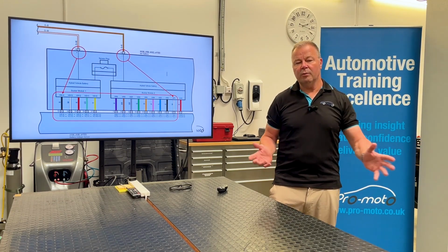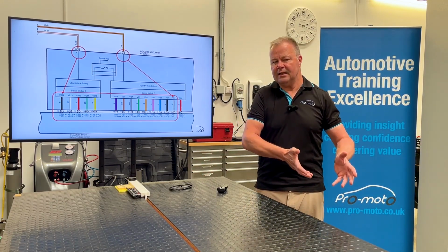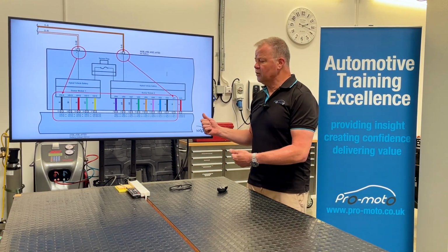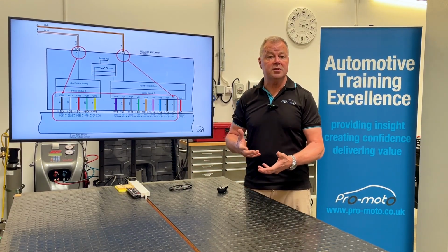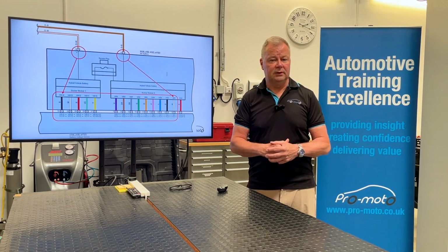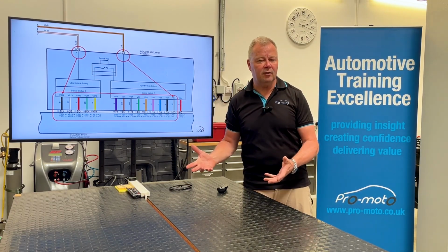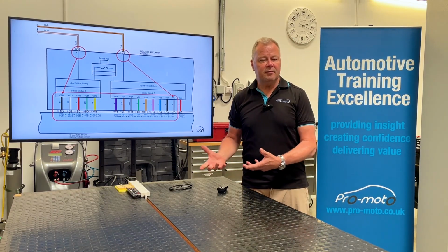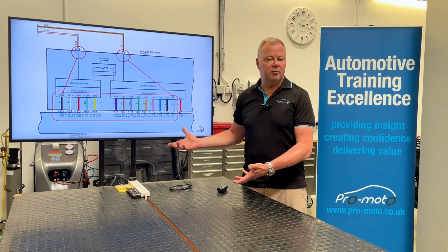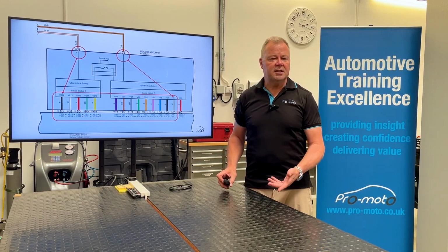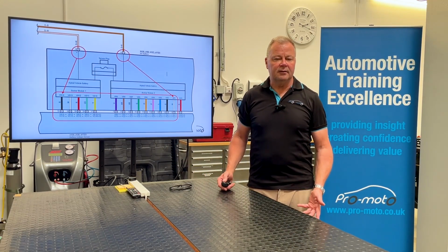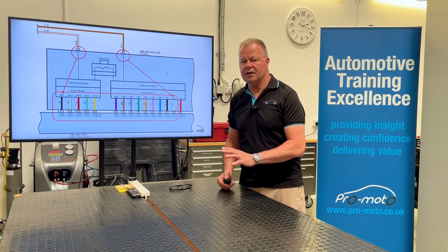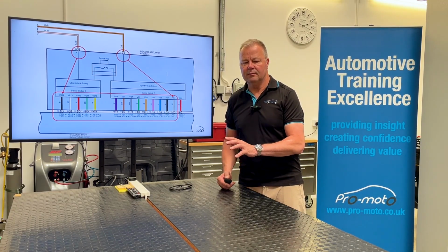Okay, so when we go into the battery, then we can use our data list, our live data, and then we can measure the voltages across the battery to confirm which one we suspect is the rogue module. And then we can carry out a possible repair on that. Because at this stage we've got it wrong. We would say if we didn't identify it manually with the voltage readings, we can actually end up repairing the battery inappropriately or changing the wrong module, and we're back to square one again. Okay, so that's a Toyota or Lexus orientation and troubleshooting a battery.